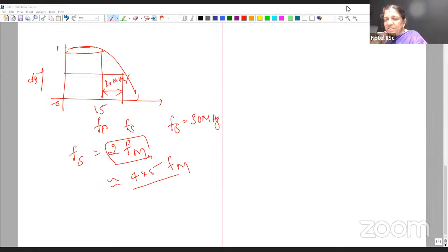What happens is the noise is distributed over the complete frequency range and then we do the cutoff, so that way the noise is spread over and we are reducing it. Earlier it used to be successive approximation ADCs, with the number of bits 8-bit or 10-bit maximum, and then 12-bit ADCs. Now we can increase the number of bits a little, and you'll see signal to noise ratio coming into the picture. So that way we upsample and then downsample later on. That part I did not cover in this course.